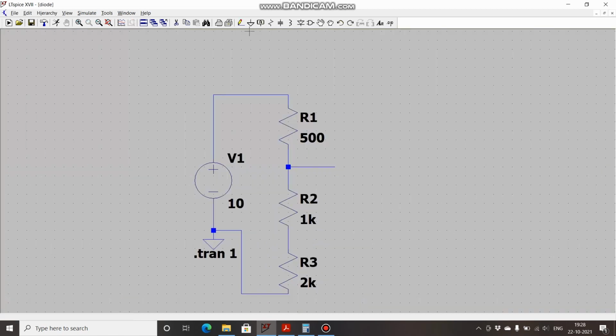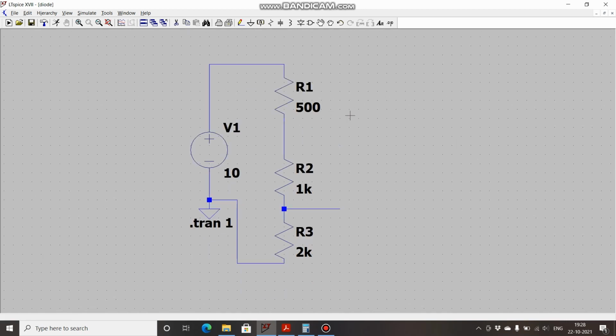Similarly, if you have to find out, let's say, the voltage across this and this node, I will remove this for simplicity. What you will do is it is simply R3 upon R1 plus R2 plus R3 times VCC, and you are done. Now let's solve a simple sum and we will see how this voltage divider rule is useful and makes your calculations much easier and simpler.